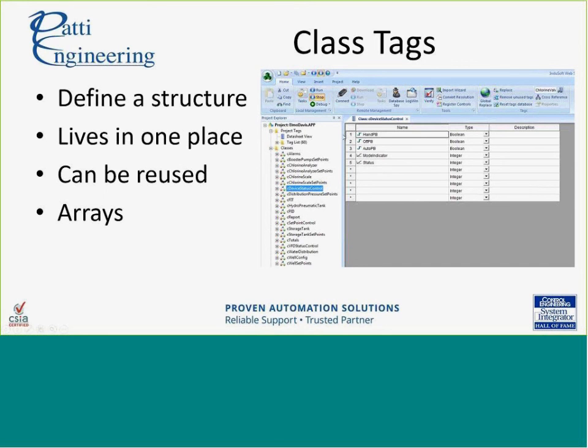And each one of those handoff, auto control symbols had the same tags used for them, so I created a symbol. If I needed to add an additional tag to this, I just edit it here, and all of my class tag instances elsewhere would be populated and modified.